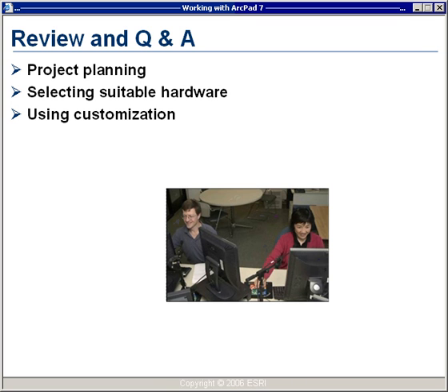Ken from Albany asks, if data is created in ArcPad while in the field, can that data then be checked back into ArcMap using the check-in function? I presume what's meant here is while you are in the field, can you check that data back in? And the answer is not really. You need to connect your mobile device to the PC that you use to check out your data, move the data from your mobile device to that PC, and at that point, that data is available for checking in and updating your geodatabase.